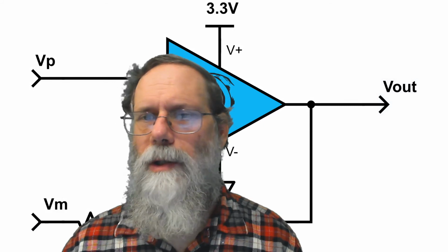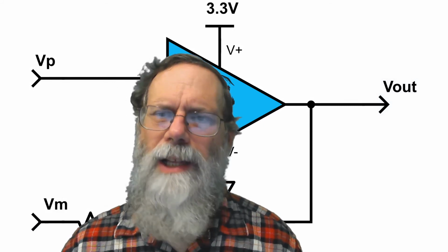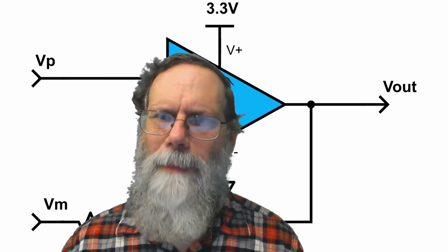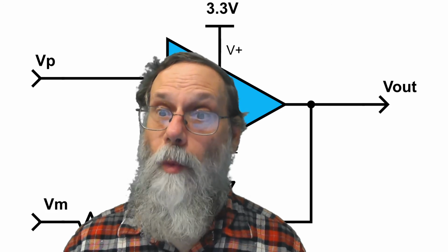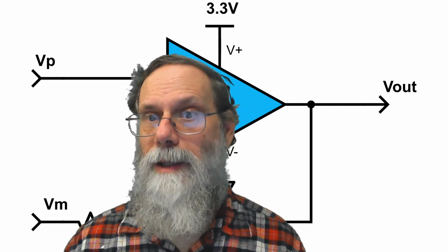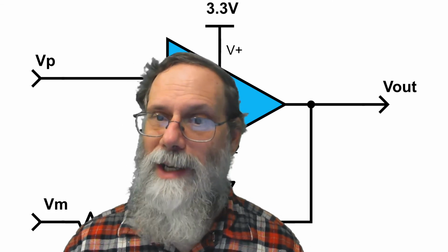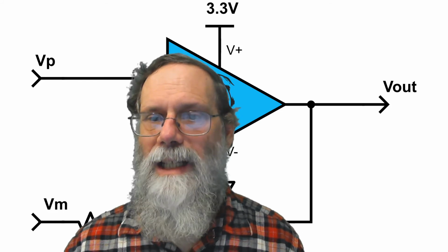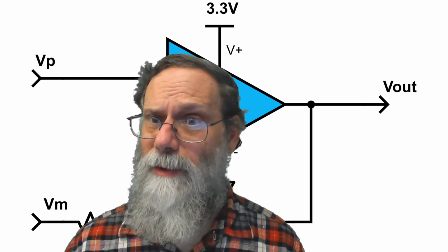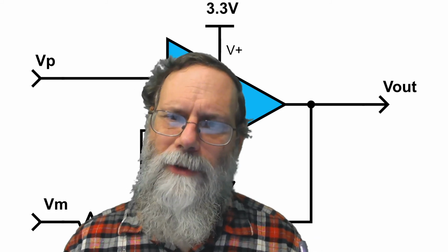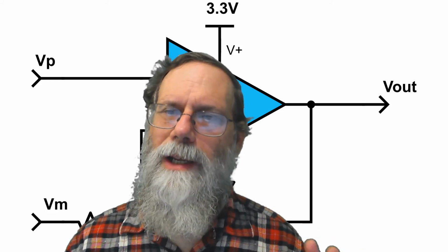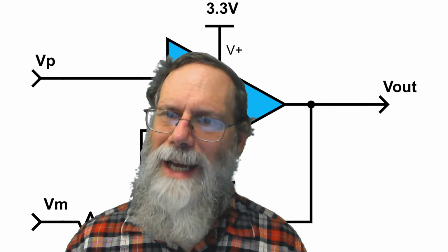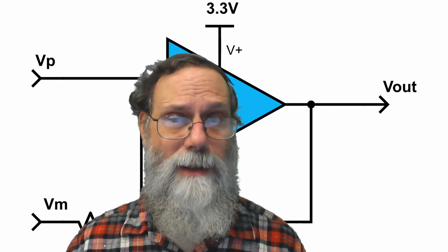All right. So what else do we need to know about capacitors? Now, there's one thing that may be bothering you a little bit, and that is the impedance of the capacitor is purely imaginary. It's 1 over j omega C. And if you multiply top and bottom by j, it's minus j over omega C. So it's a negative imaginary number. What does that mean? Well, you can think about it in that the current and the voltage aren't in phase with each other. The voltage and the current don't go up and down at the same time. They're doing it at the same frequency, but not at the same time.